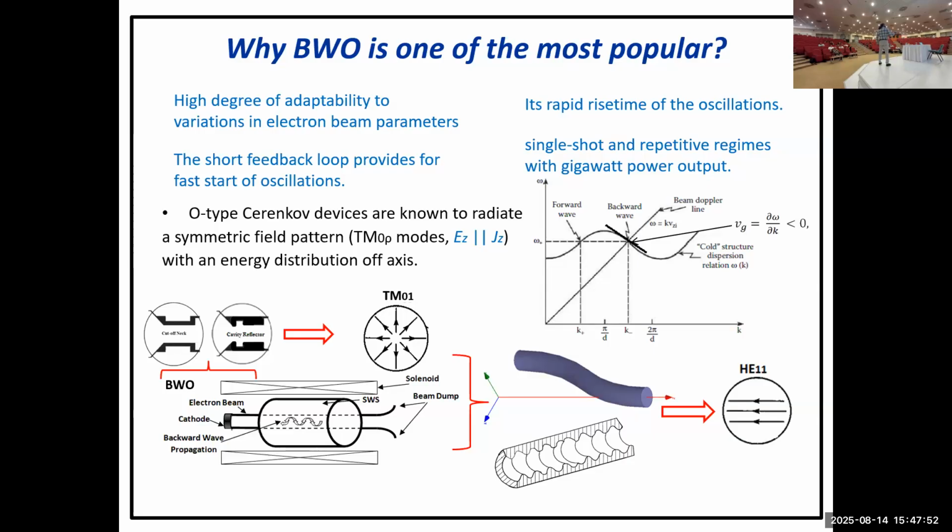Or there is another way, which is a cavity resonator. This cavity will resonate and reflect the same mode pattern. TM01 will be reflected as TM01, donut shape. And this is the donut shape, meaning here is the concentration of energy. At the output here, sometimes they use a mode converter, and it can be a periodic structure with no beam.